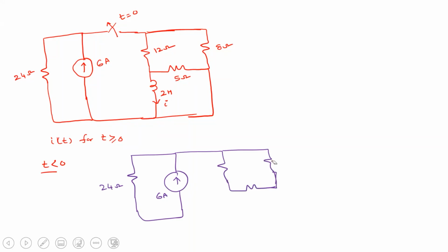Sir, the 5 ohm resistor is removed now. Wait. So how will this act? How will the inductor act? Short circuiting. So this inductor will act as a short circuit, right?